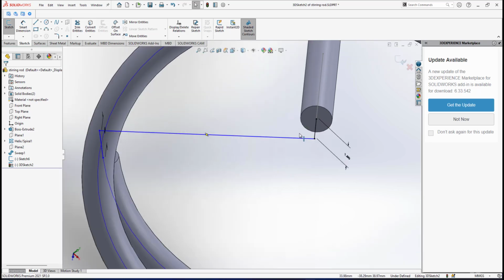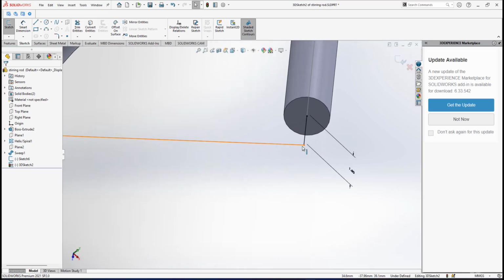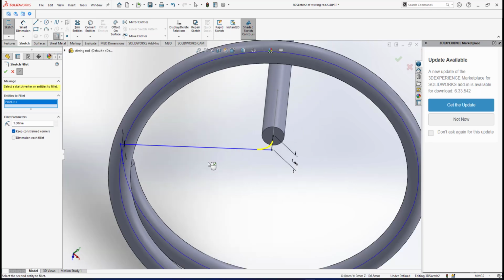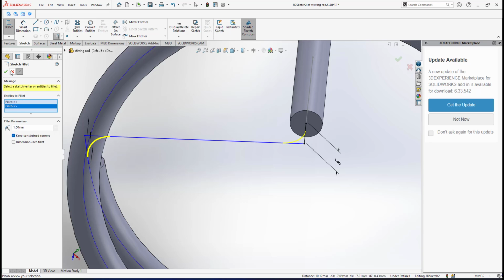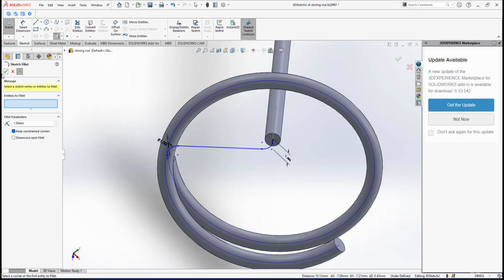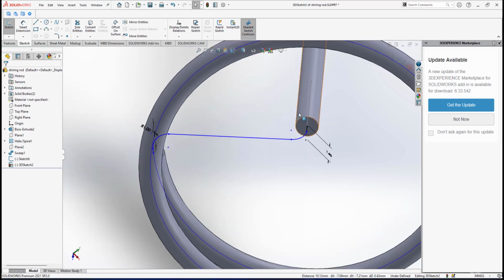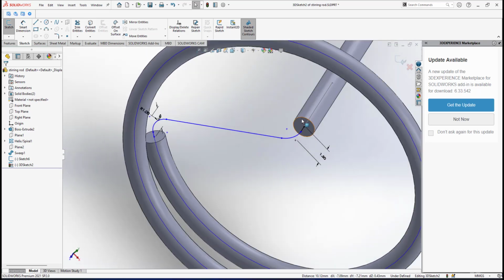to create sweep. All right, here at the corner I need to put a fillet of about 1 millimeter radius at the corner, so to make a curve. And also at this point, so I have a curve there. Okay, this path, right? This will be the path for me to do sweep. Since the cross section can be this surface here, and this will be the path. All right, I exit the sketch.